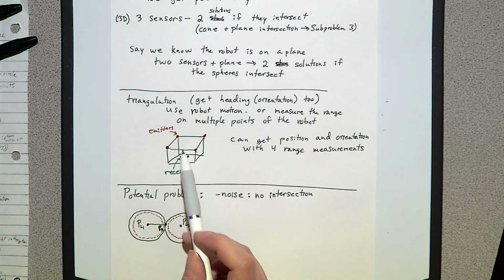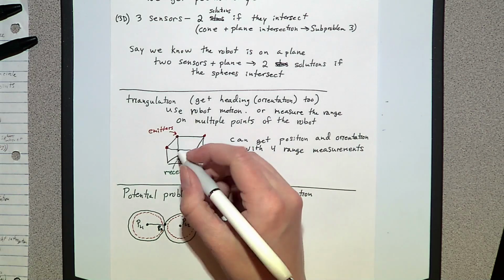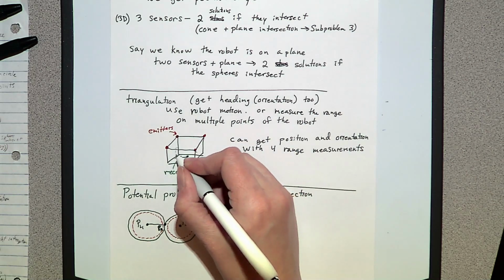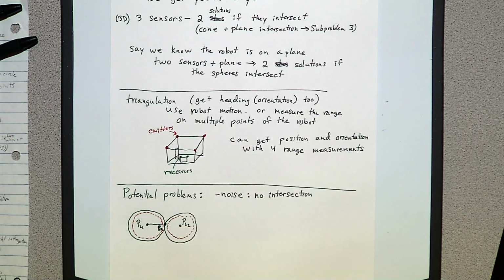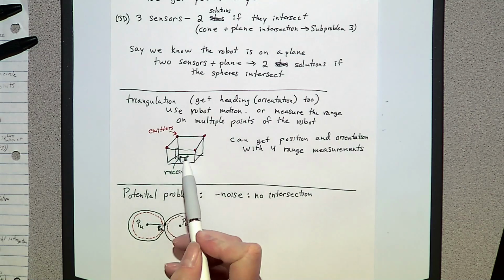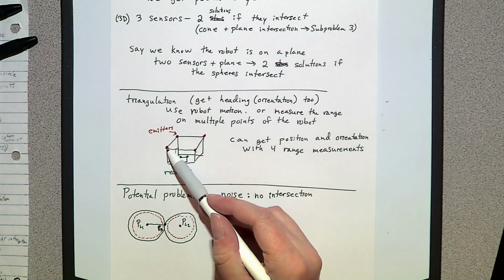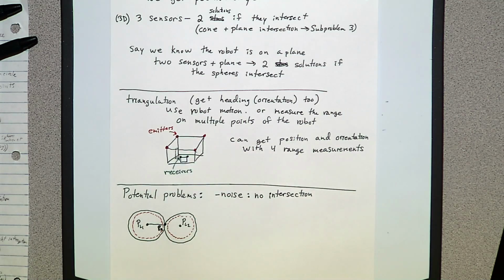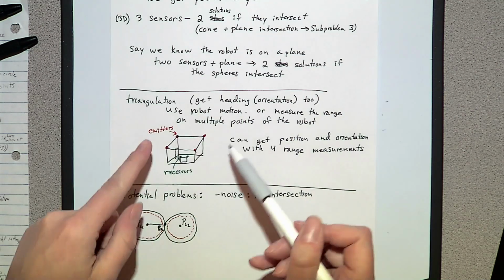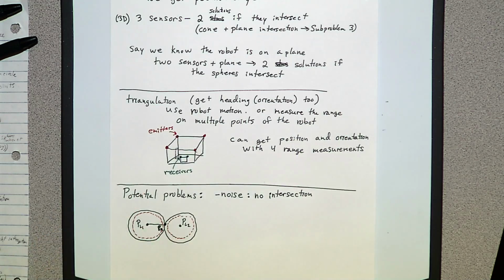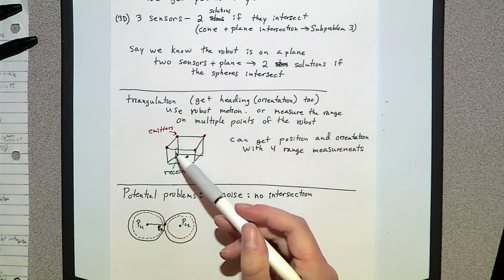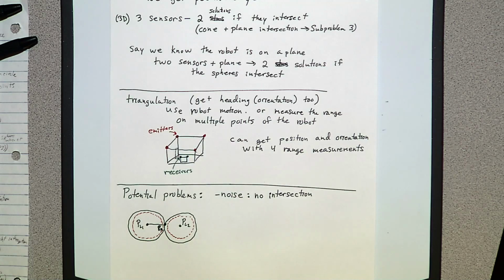And if you have a case like this, what happens if there's, say, some kind of cabinet there, and the robot happens to be right next to the cabinet? Now all of a sudden you've lost line of sight to one of your sensors, right? And so even though you had a sufficient number of sensors to be able to tell your position and orientation, now all of a sudden one of those went offline, and now you've lost some of your critical information.